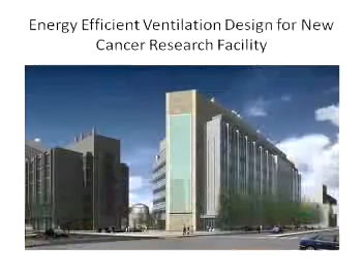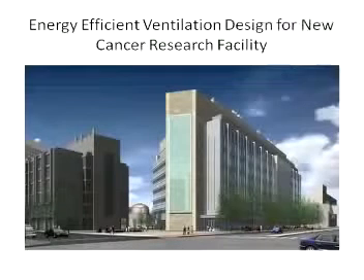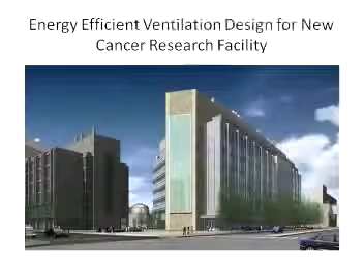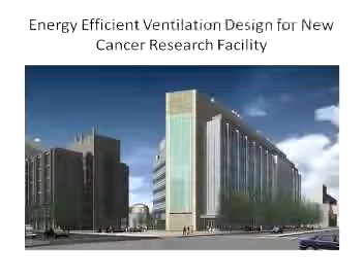Now, this is an example of actually the newest building on the MIT campus, the Koch Center for Cancer Research, which was just dedicated about a month ago. And what we found out in that case, and a colleague of mine, Les Norford, worked with some people from the safety office, is even when the fume hoods are left open, the amount of air velocity that needs to be sucked in for safety's sake was grossly exaggerated, and we could reduce that by 20% and still assure people of safety.